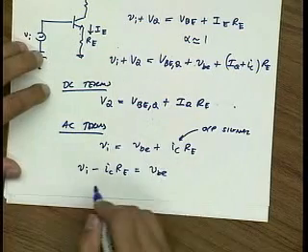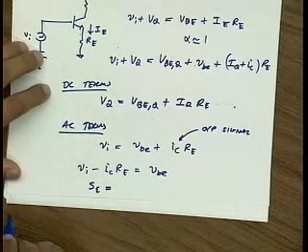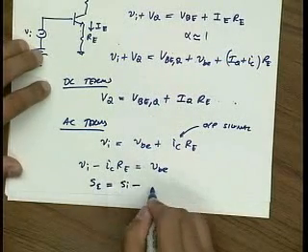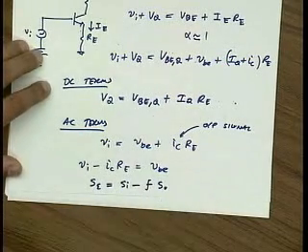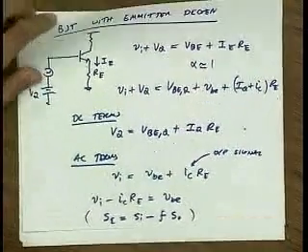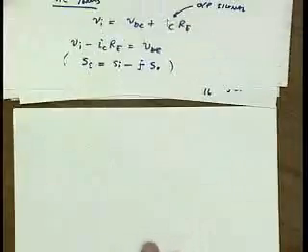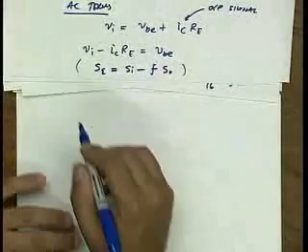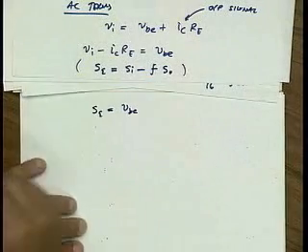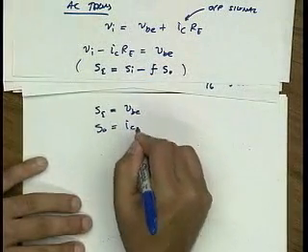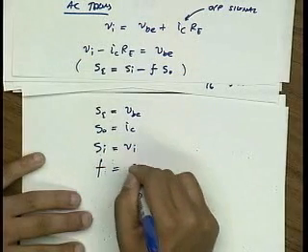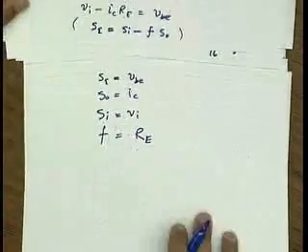In other words, some error signal is being generated, which is the VBE, which is the input minus some fraction of the output. So we see that emitter feedback looks like an idealized feedback system where the error signal is little VBE, the output signal is IC, the input signal, of course, is Vin, and the feedback factor is just RE.